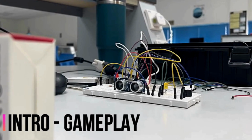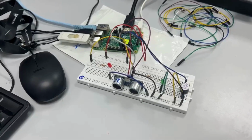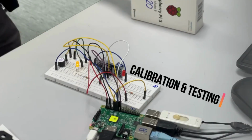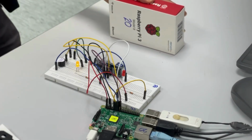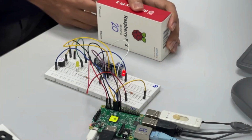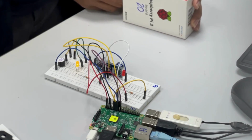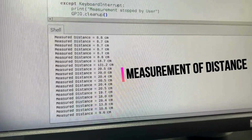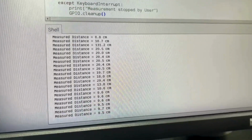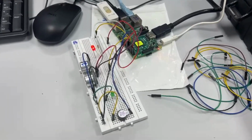This is the result. This is the prototype in its schematic version. Here we can see the components used for the gameplay. This is during calibration and testing. The yellow LED blinks indicating a safe distance between 30 cm and 10 cm. This shows when an object is moved further than 30 cm, indicating safety. This shows the measured distance using the ultrasonic sensor as the box is moved every second. When the sensor detects an object within 10 cm, the red LED blinks and the buzzer sounds.